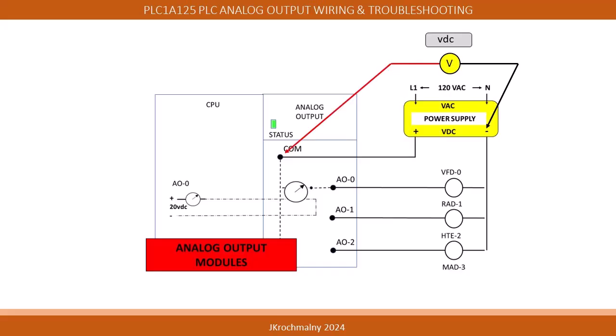Since the power supply feeds the reduced voltage DC to the output module, we should read that step-down voltage DC at the module's common terminal. One more step to be taken when verifying voltages DC involves voltage actually registered on the PLC output module terminals. Voltages appearing here should be the same values as the output voltages of the power supply. The previous steps involve DC voltage measurements with the circuit power being applied.